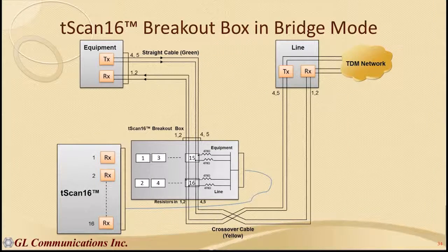So there's a bridge mode and a monitor mode. Those are two ways to handle a customer environment, and our TSCAN 16 is compatible with both. It's non-intrusive and allows one to easily use our TSCAN 16 in an existing environment and monitor that many T1 and E1 lines.